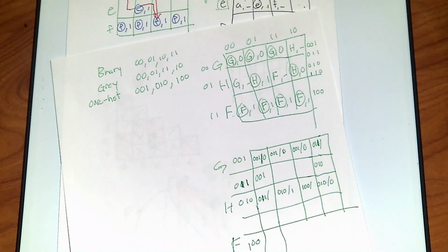But I don't know about some other conditions, like splitting states, all kinds of stuff like that. So there's a little more work involved, some thought, and I'll give you that process. But this gives you the basic one. You've got at least three basic coding methods. You've got the foolproof system, and the other one you usually only use Gray code. You do that if you need something really small, something really elegant, then you do the extra work.